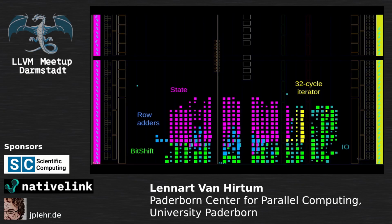And so then I could actually synthesize it. And the fun thing is, because we are designing hardware at this very low level, we can see from the hardware we've generated, and we can loop it back to our code that we have written. So through the module hierarchy, you can mark, say, the state module, the row adders, the bit shifter, and the iterator, and these all pop up as specific regions in our hardware design. And of course, from the names in your timing reports, you can also go back to your hardware design as well.